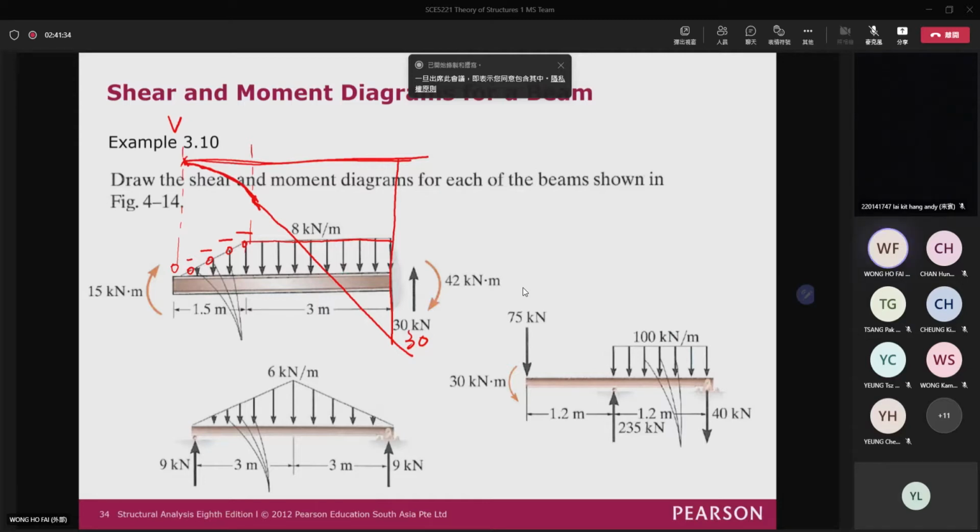And then from the shear force diagram, I can draw the bending moment diagram. You can see that this one is equal to 15, because this one can make the structure bend in concave downward, so it is a positive value. And then you know that this one is a negative value for shear, and then more and more negative, very, very negative.